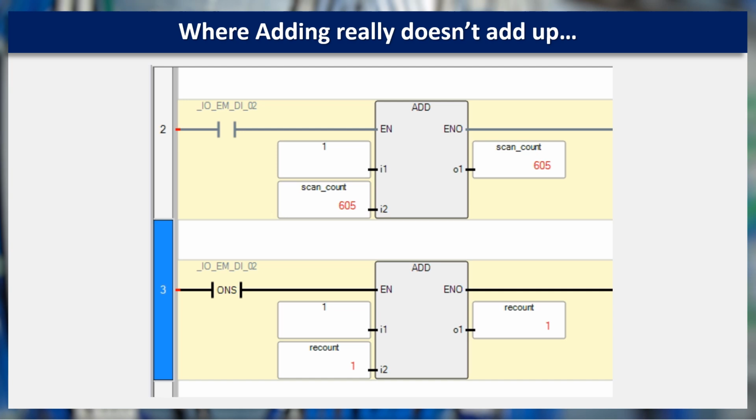I'm going to flag it again, and the bottom rung 3 is 2, but the top rung says now 1300. The reason that there's a difference between the two is the leading instruction before the add. On the top, we find our usual execute if charged. But on the bottom, we have a new instruction that says ONS.